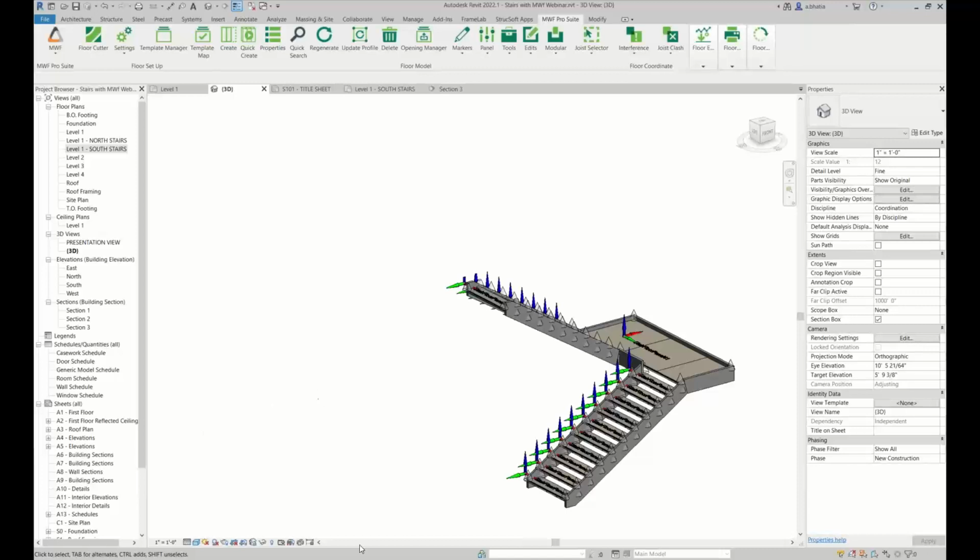You can create a sloped slab and have the stringers as your end joists. Maybe that would be a way you could create your stringers. Maybe for the landing, for sure, you could use that method. But by default, no, we don't really have a way with MWF to create a stringer.